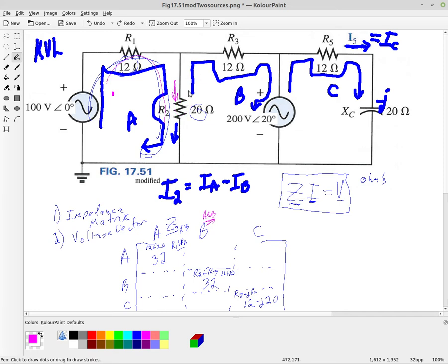And so therefore, we add together all the impedances in here where both A and B are shared. Okay, so R3 is not shared. IA does not touch R3, so we don't include R3. And so we're only taking the ones that are shared, and we're going to subtract those off. So I'm going to subtract off 20. Okay, so I'm subtracting off 20 because of R2.